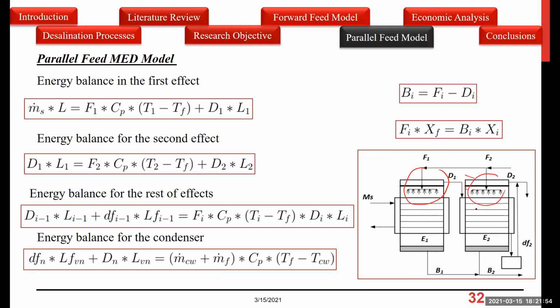The sensible heating here is going to be from TF to T1, and here it's going to be from TF to T2 and so on. So in every effect, there is a component of sensible heating and then a component of latent heat. This is what you see here. Again, the L is nothing but the HFG.